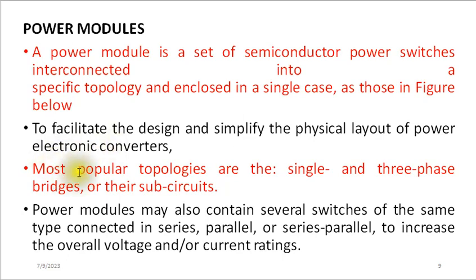Then the most popular among these topologies of power modules which are available are either single phase bridge rectifiers or 3-phase bridge rectifiers. These power modules have several switches inside, as we have already mentioned, and these switches are connected either in series or in parallel, or even a combination of series and parallel to one another. And the reason why we use the series and parallel connection is to increase the voltage or current rating.